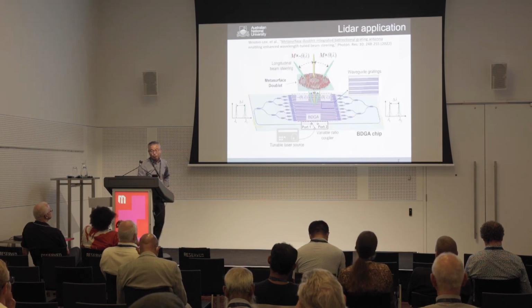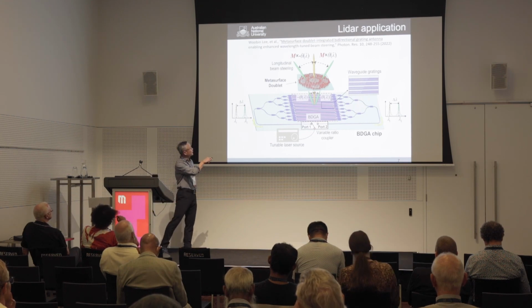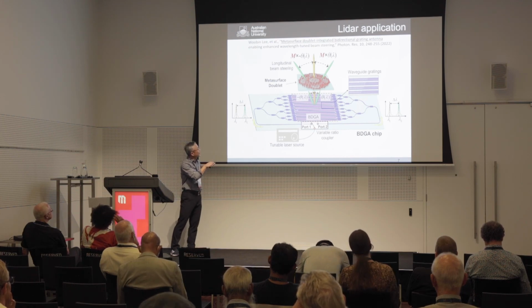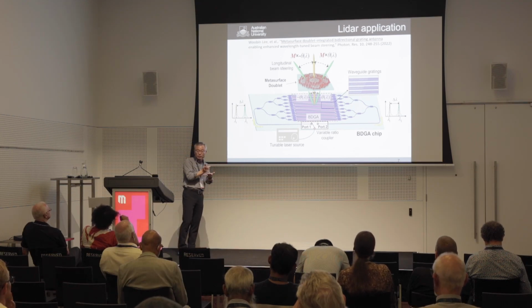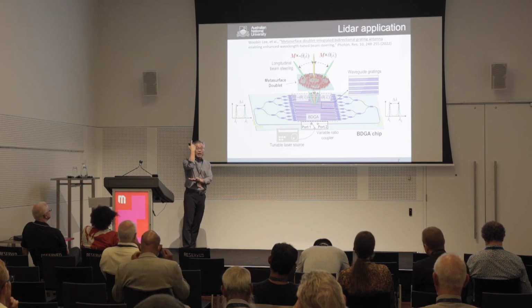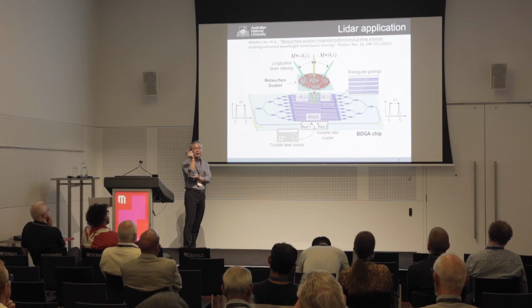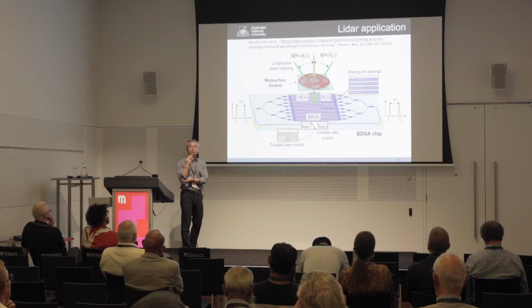Using this, we integrate with a silicon nitride waveguide for LiDAR application. Here, all the light goes through and branches in the MMI splitter. And then there's a grating coupler, looks like this. The wave goes in, and on this grating, it goes up, emitted outside. But by changing the wavelength of this input light, it can slightly scan. The scanning range is about 7 degrees when we change the wavelength about 100 nanometers.